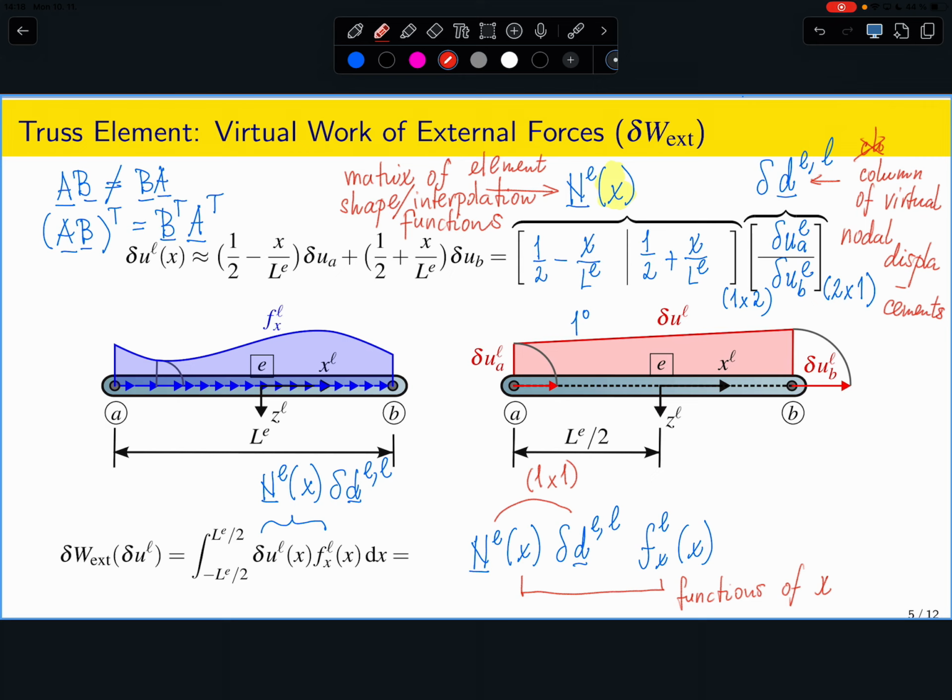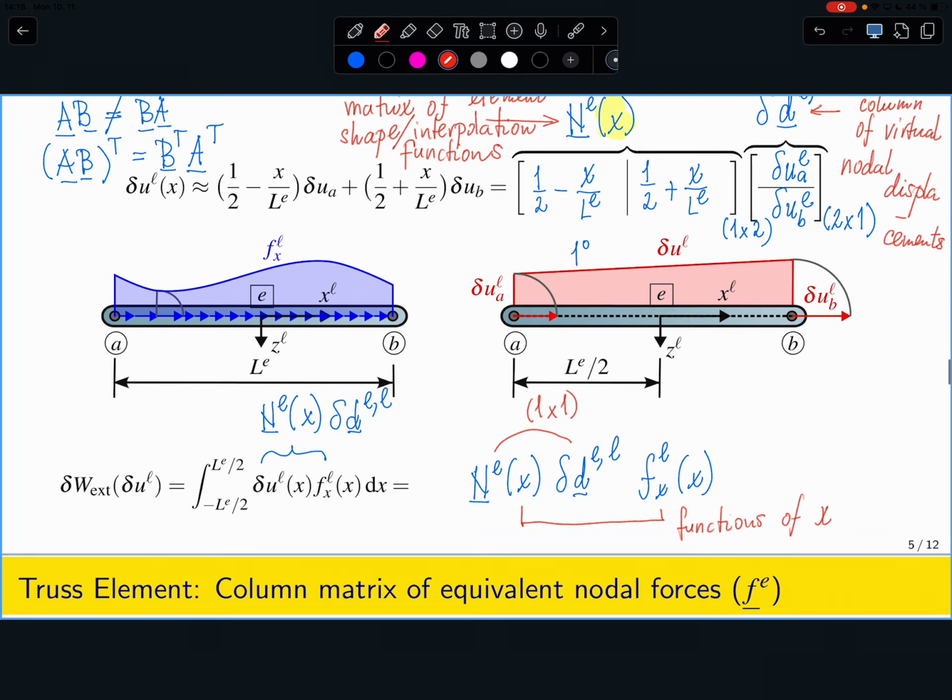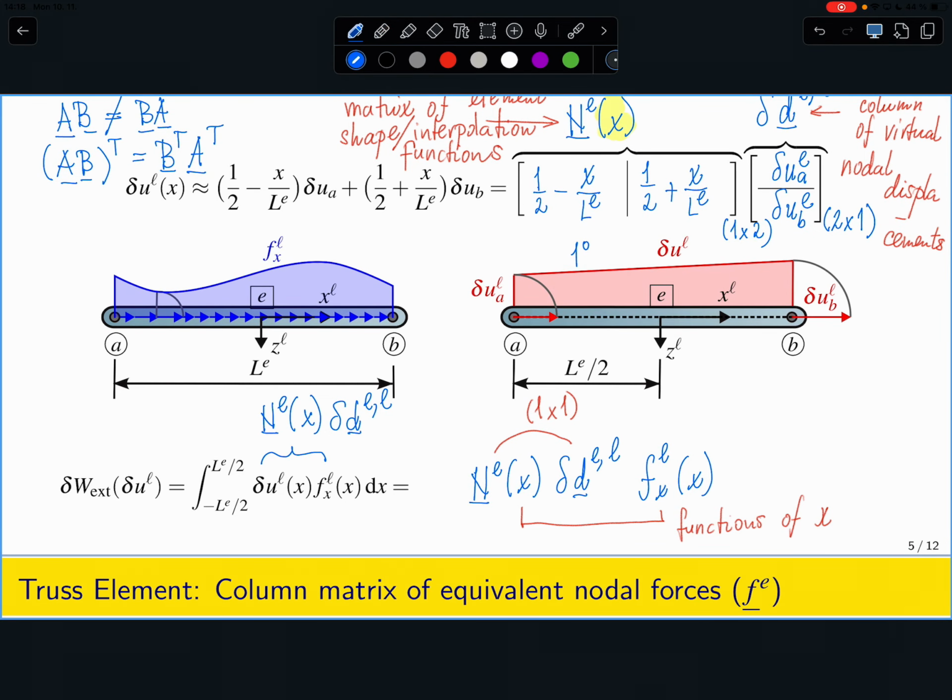This is just the virtual displacement, horizontal one, which I see at a cross-section x. So if I just take one number and transpose it, it will be exactly the same amount of information. So if I now imagine that I will take the multiplication of those and transpose it, I can get this very ugly object, this virtual displacement, out of the integral.